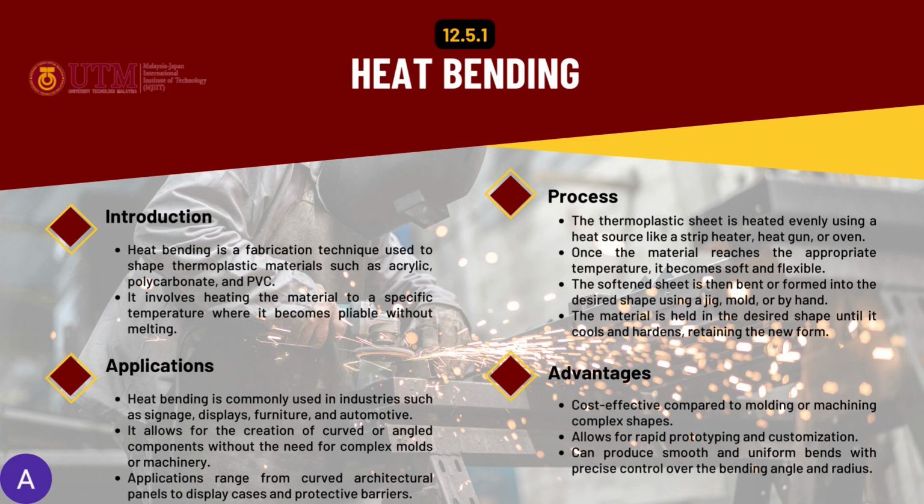So the first one is heat bending. Heat bending is a fabrication technique used to shape thermoplastic materials such as acrylic, polycarbonate, and PVC. It involves heating the material to a specific temperature where it becomes pliable without melting.